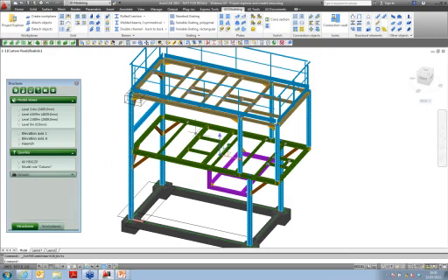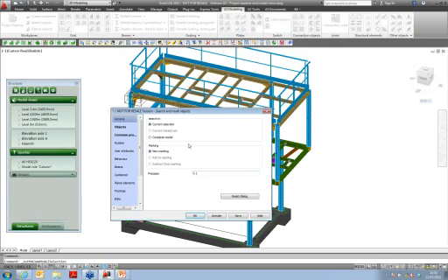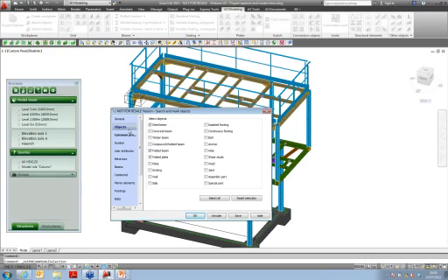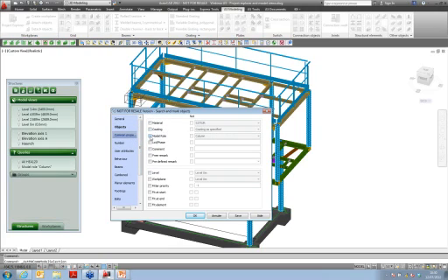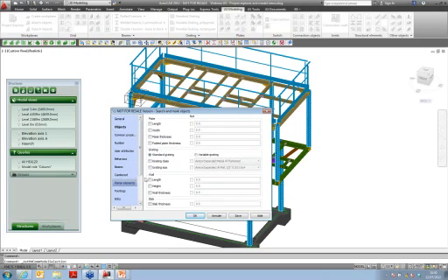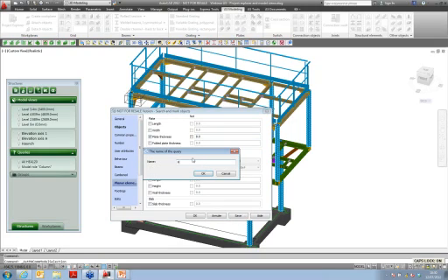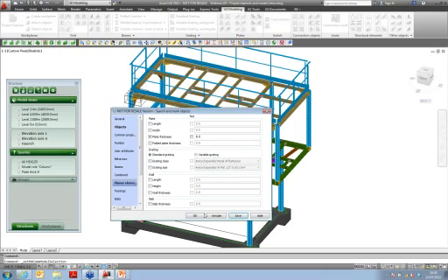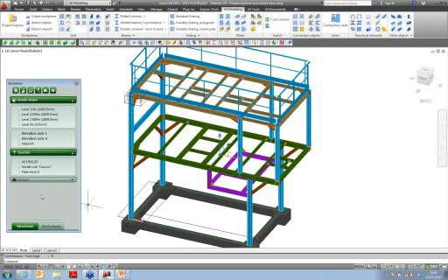So the query can also be created by going directly to the search filter. I can go to this dialog, which says that on my complete model I'm looking for, for example, plates. No specific model role, but concerning planar element, I'm looking for plate thickness equal to 8. I can save, give it a name, plate thickness 8, press OK, OK, and then the query